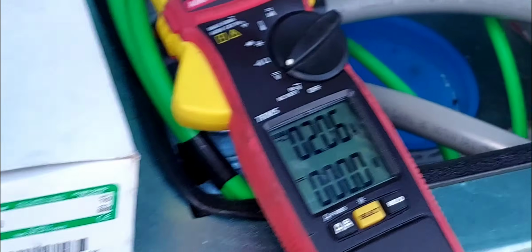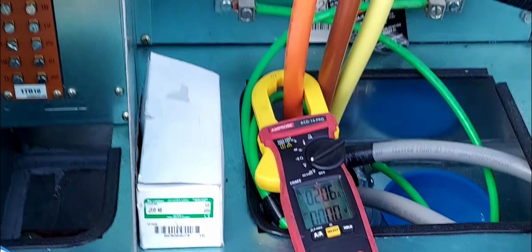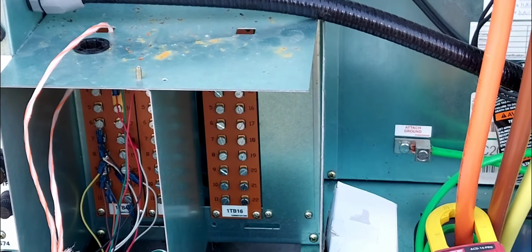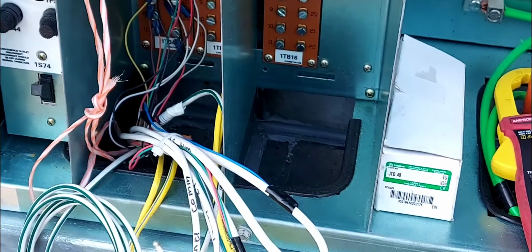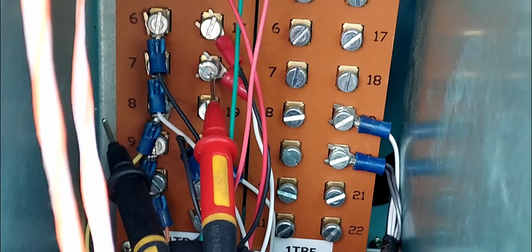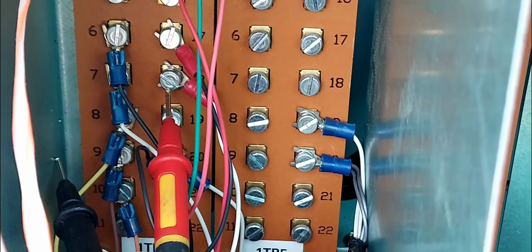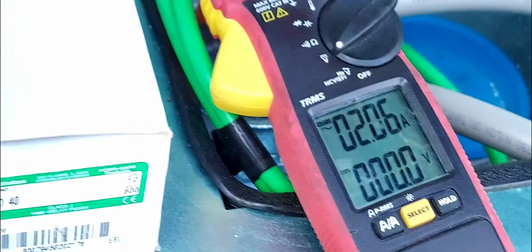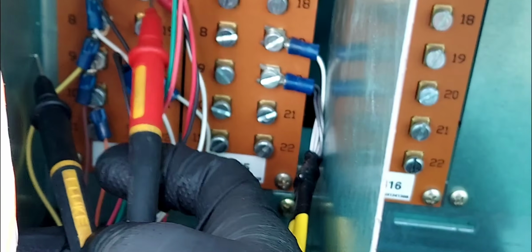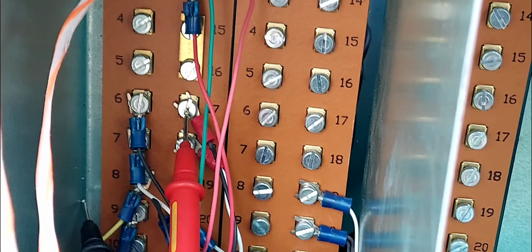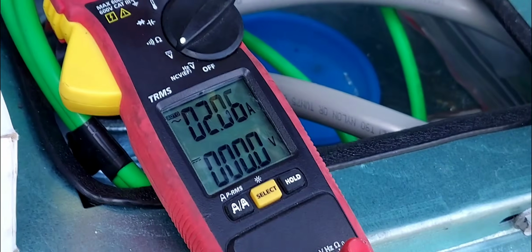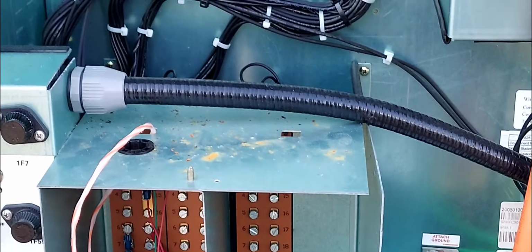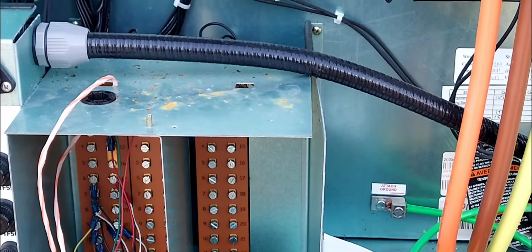I got 0. So either those points are currently closed, or there's no potential on the terminal. Let me go ahead and check for potential. I'm going to go to chassis ground, nothing. We'll go to 17 and chassis ground, nothing. All right, so next step, I thought I'd read something if that was open,